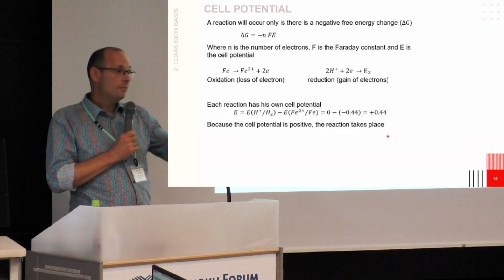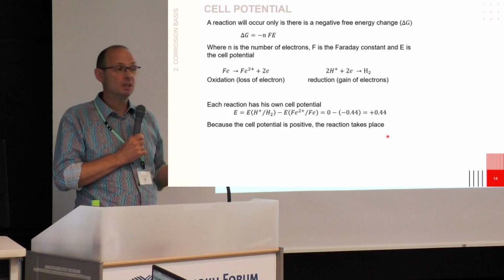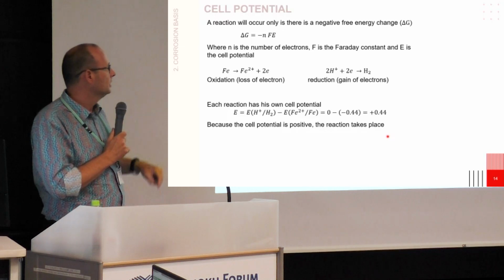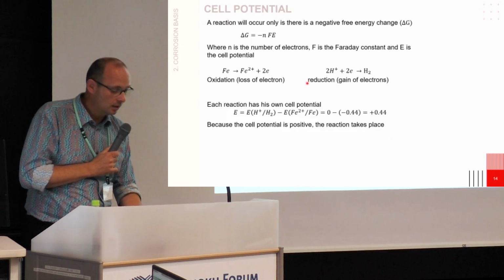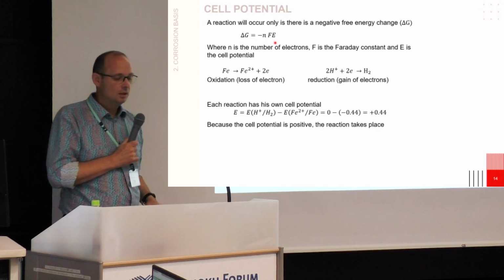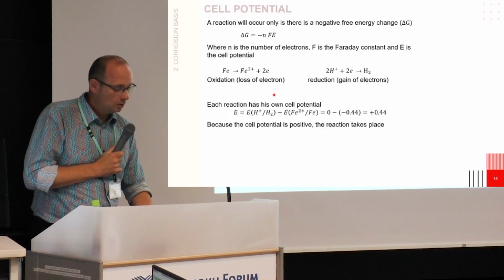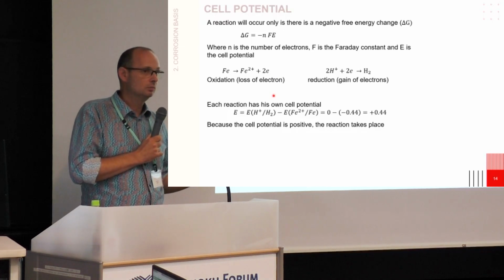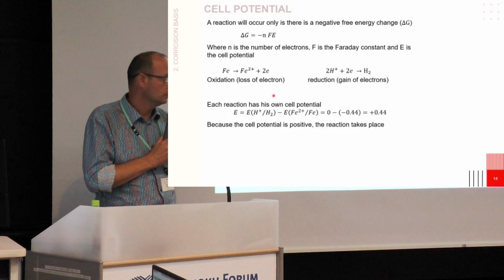So to have this exchange of electrons, we have to look at the thermodynamics. Here is a small example, but it's very helpful. In corrosion, we are not using the Gibbs free energy, but we are using the potential. And what we are doing is we just compare potential between the cathodic reaction, which is catching electrons, and reactions that are releasing electrons, the anodic reaction.